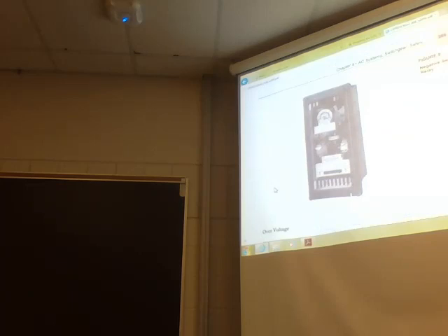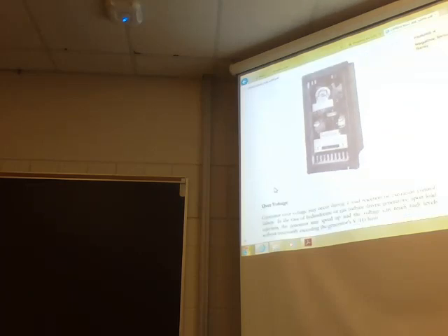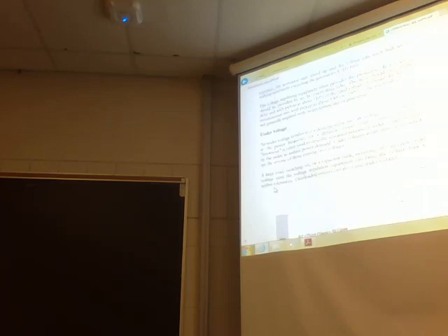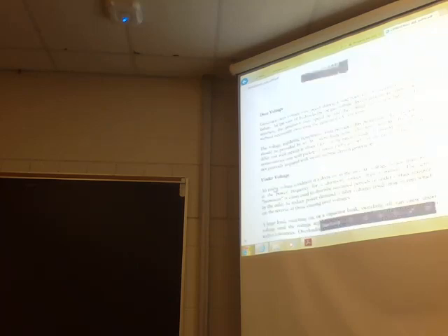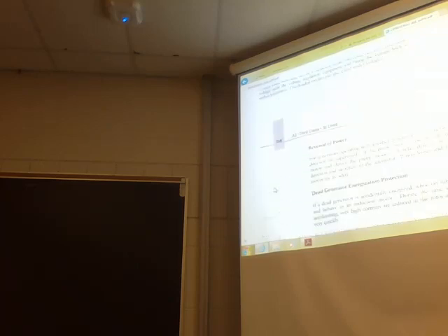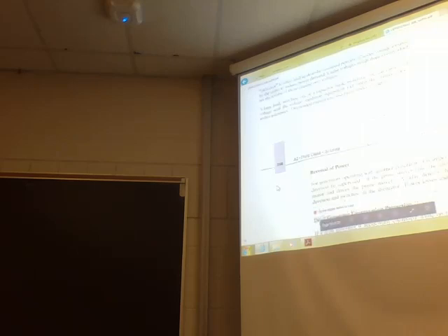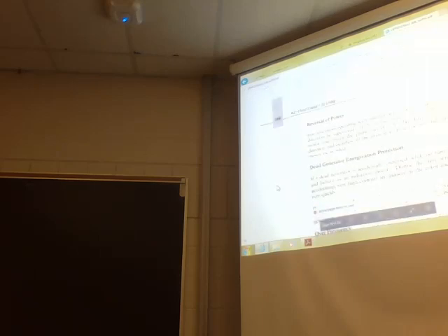Undervoltage protection, overvoltage protection, reversal of power. For generators operating with another generator, it's imperative that the power direction be supervised. If the prime mover fails, the alternator operates as a motor and drives the prime mover. A relay detects the reversal of power direction and switches off the alternator. Power losses and damage to the prime mover are avoided.